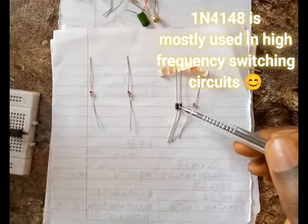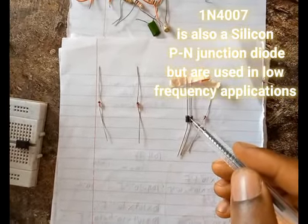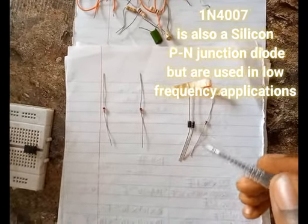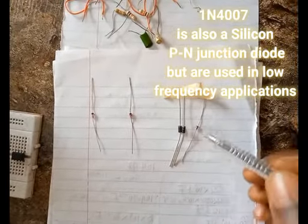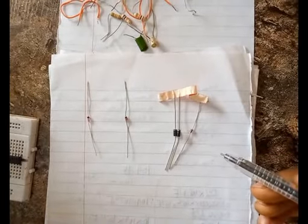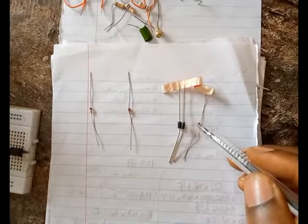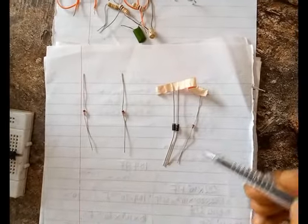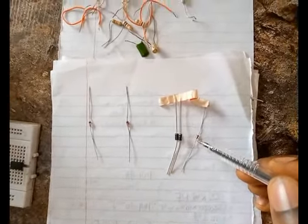We don't apply the 1N4007, that's the number for this one. This is a PN junction diode. We don't use them in a circuit where you expect high frequency switching, but we make use of the 4148 wherever you have high frequency switching. That said, because I really needed to point this out, they usually look alike. So check it and be sure that the number written on it is 4148 for you to know the difference.